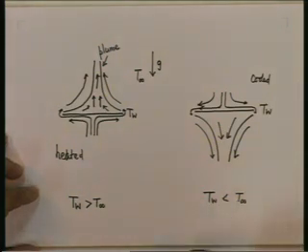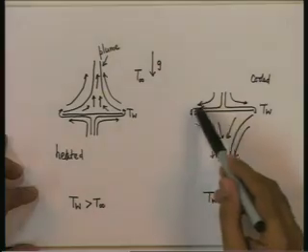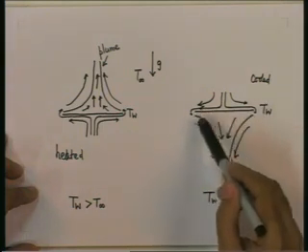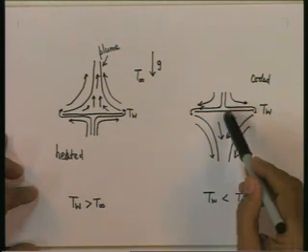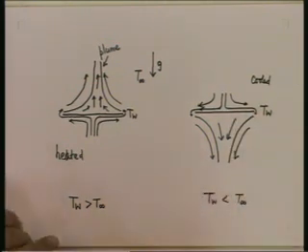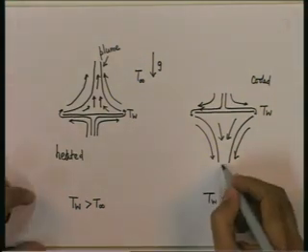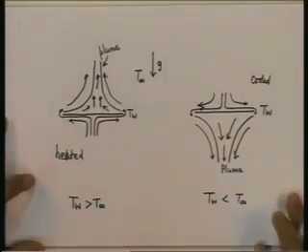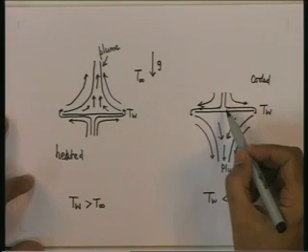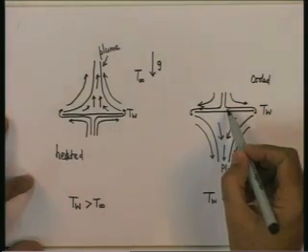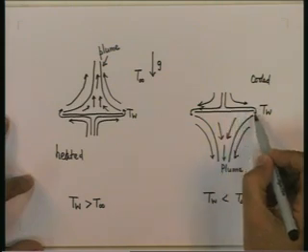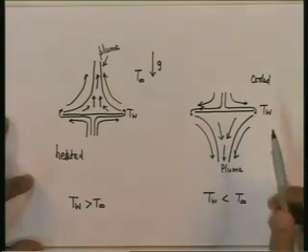However, if the surface is cooler compared to the surroundings, then the fluid below the surface will become denser and will try to descend. So, this is the plume which moves down in this case, whereas the fluid near the top of such a surface will try to stick to the surface, will drift towards the edges and will try to escape downwards.